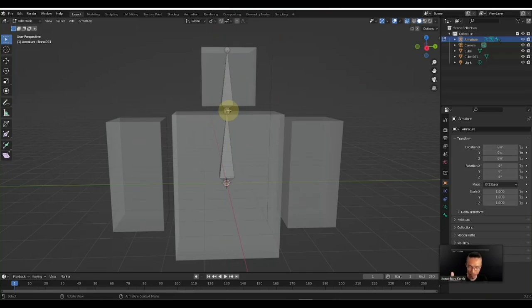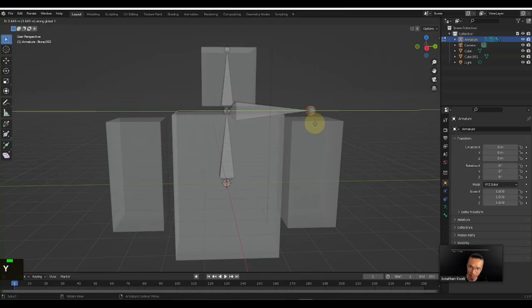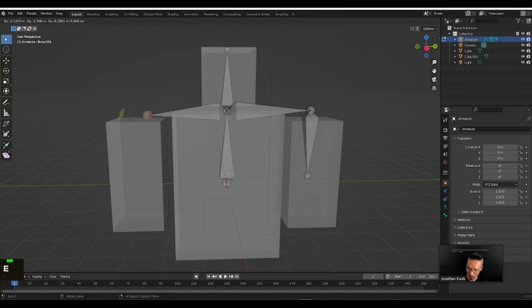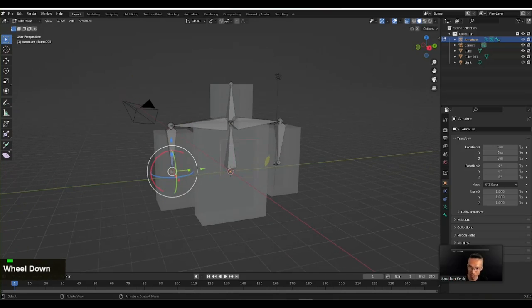Then after that, you go back down to this end point over here, because we're going to extrude out two points from here. So E once again, and we're going to leave this along the Y axis. Then we press E again to bring this down along the Z axis. Again, where this ends doesn't matter. E, Y, E, Z. So that's basically it.